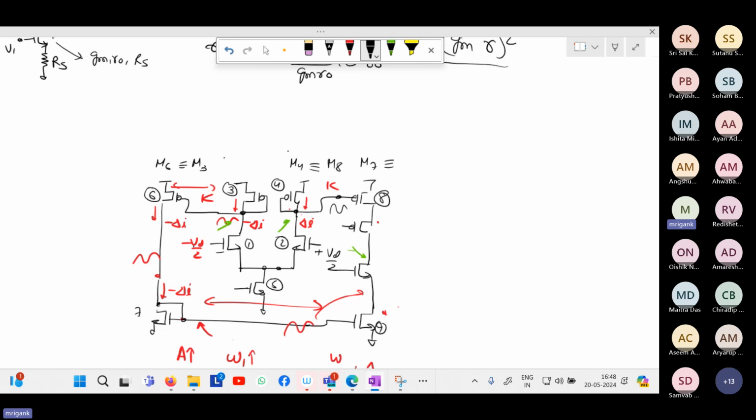So now whatever gate voltage of M6 is there, I will bring it here. Here it is not connected, so here I have not drawn the dot. That means it is not connected. I can put a jumper, but a jumper becomes a little clumsy and doesn't look good. Generally, this is the practice. So now I can use a current mirror structure like this.